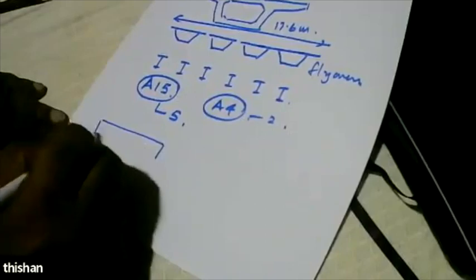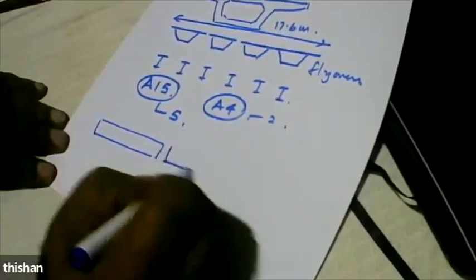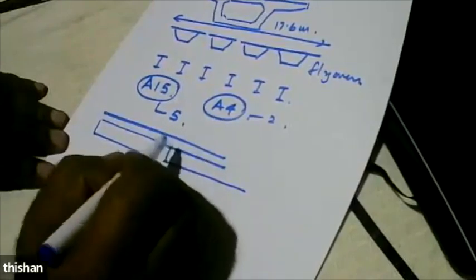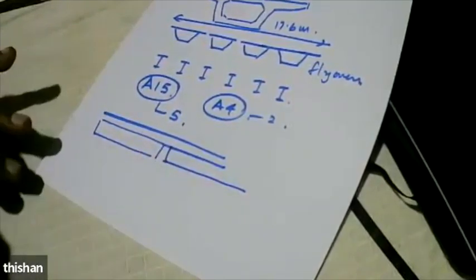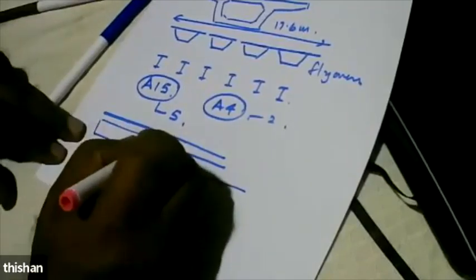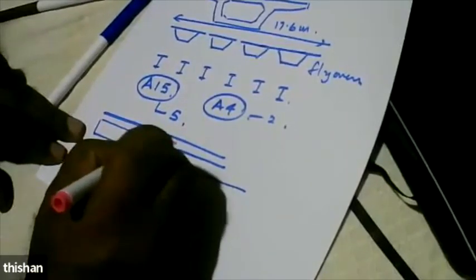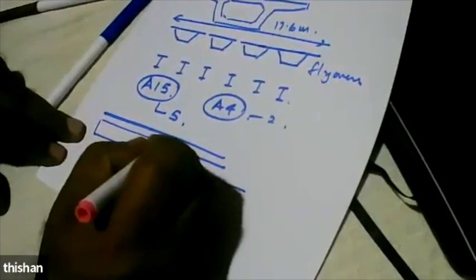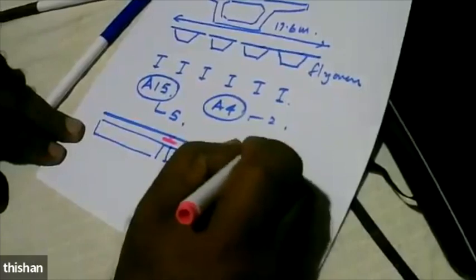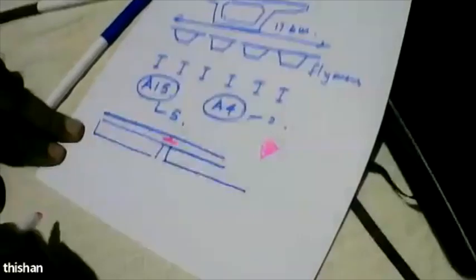We have the beam, and we have another beam, and we cast the top slab continuous. After casting, actually we cast it in 2 stages. So here we had a double bar, and we cut a groove and fill it with polysulfide.